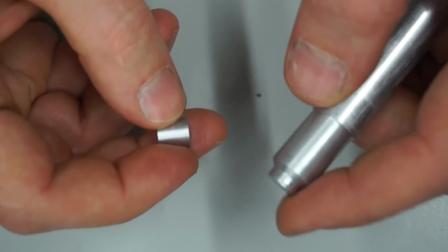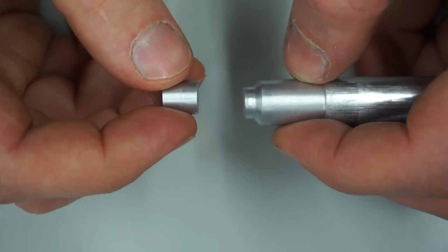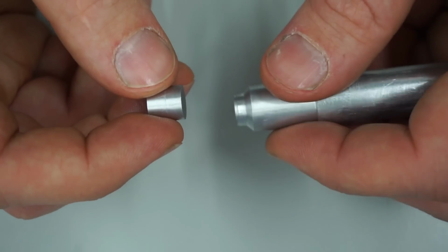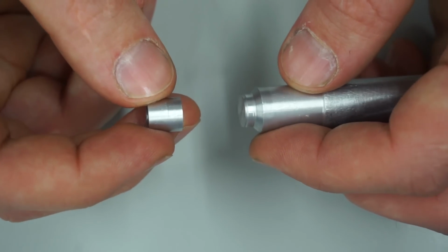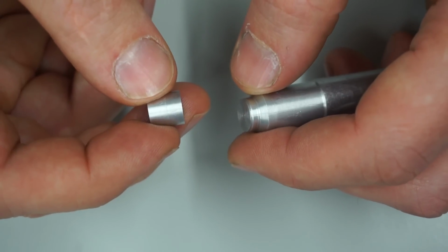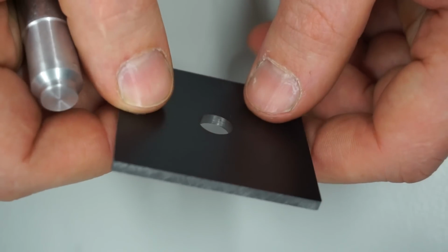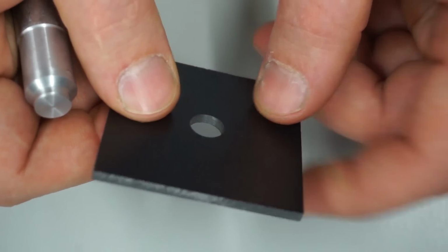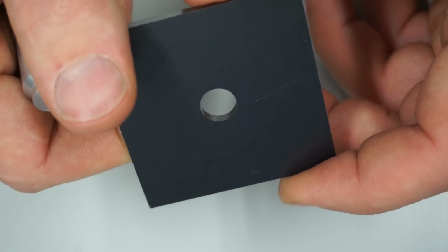And if you wonder how to make such parts burr and chamfer free, you can, for example, gang 4 or 5 blanks with super glue together between these two arbors here. Take this one in the chuck or in the collet in the lathe, put the tailstock here and turn them to dimension. Then you must break them apart and discard the outer ones. The inner ones can be kept for this experiment. They should have a sharp and exact corner. Same works for the sheet. You can gang 4 or 5 of them together with super glue, ream them to dimension and then break them apart and discard the outer ones and keep the inner ones.